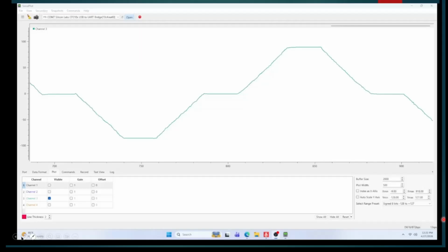So basically, when you're starting your system, you always have a little bit of a problem with the angle. Yes, a very small failure, not failure, it's inaccuracy, I should say. And then as time goes by, the inaccuracy increases. But that's why we use the accelerometer to get rid of that drift in our complementary filter. Okay, with that, I think we're ready to continue with our presentation.